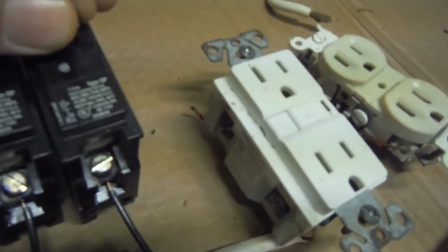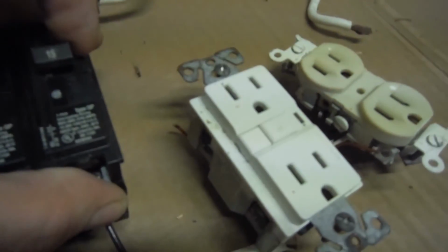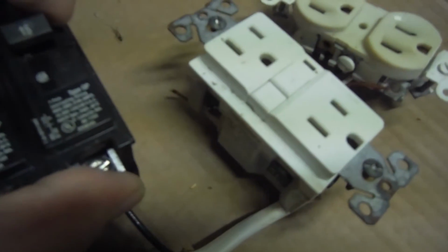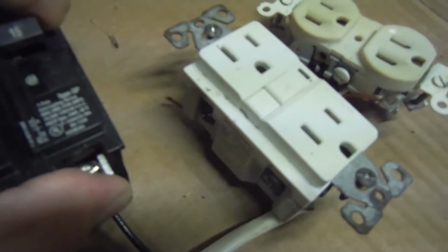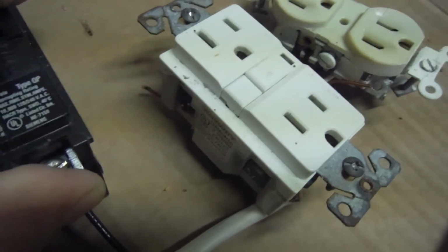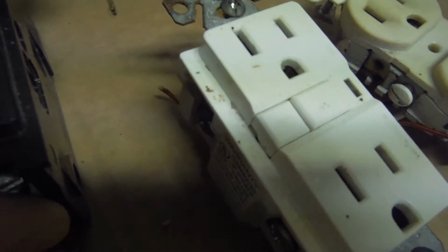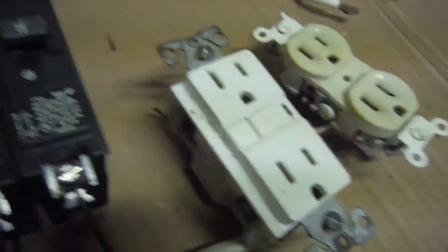Another way, I did another 15 amp breaker over here. Another hot line coming off of there. Neutral and ground are hooked into, well, I guess it would be the ground bar. But it goes off, and this would be like your typical water type situation, like your kitchen, your bathroom, stuff like that. They should all have a GFCI. Usually, if there's two bathrooms right on either side of them, they'll put one and one and then let it go at that. And the other side will have a regular outlet like this, and there's no need for multiple GFCIs because then there's more chances of it to fail.